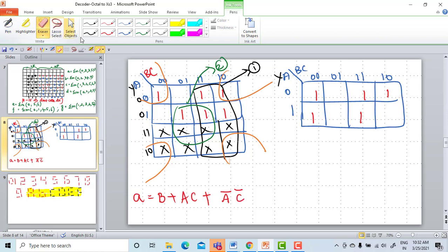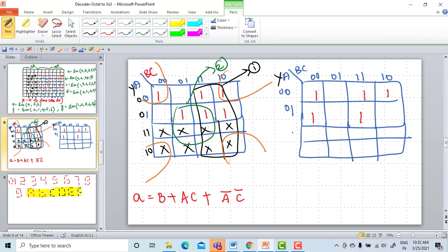So what I am trying to say is, you can use a 4 variable K map for getting a simplified expression. These are all X don't care conditions. So it's very much easy now. Now this is one 4 variable, another 4 variable, and the third one I can go ahead like this.